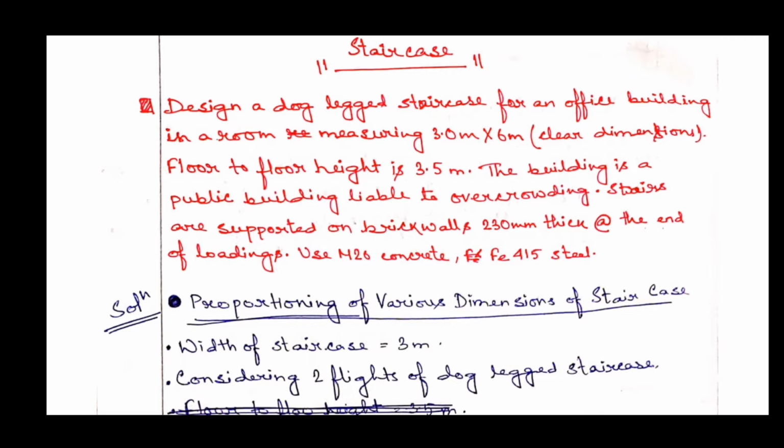Now, there are many types of staircase. Among the types, the dogleg staircase is the most economical and common format. These stairs are arranged with two adjacent flights running parallel with a mid landing. Where space is less, a dogleg staircase is generally provided, resulting in economical utilization of available space. In this type of staircase, the landing is provided at the level at which the direction of the flight changes.